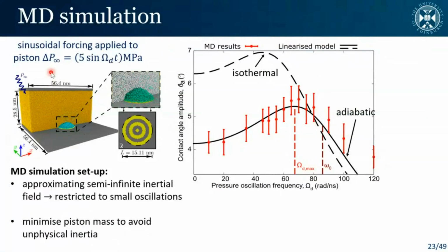So to do this, we took this simulation. You might notice this is quite large compared to the previous case. That's because to correctly capture the inertia of the liquid, which should be a far field, semi-infinite domain, we had to expand this. We weren't capturing the correct inertia with the much smaller domain. This did also limit the size of the oscillations that we could realistically input into the system. But we apply a sinusoidal forcing to this top piston, which results in a sinusoidal response in the nanobubbles.